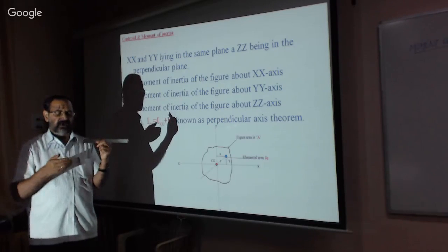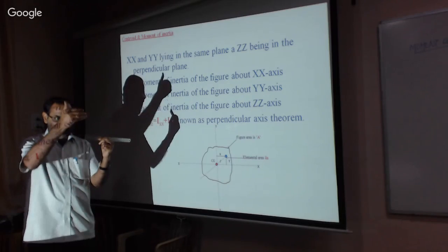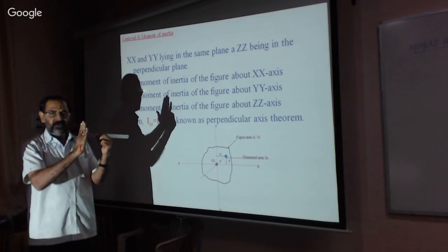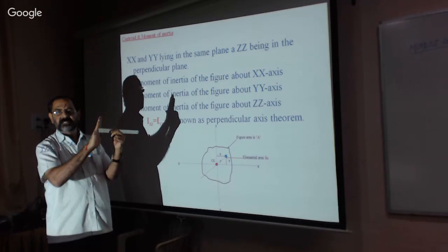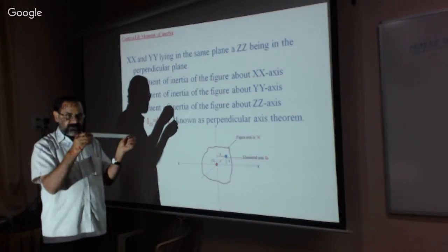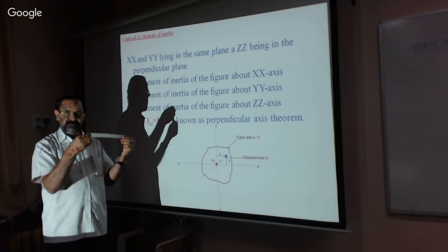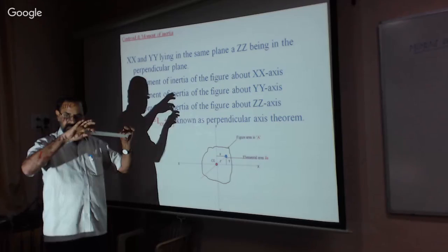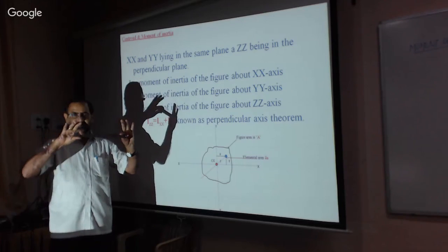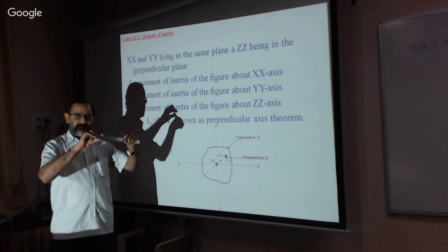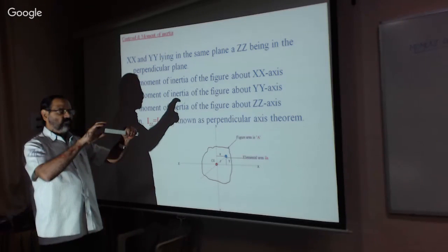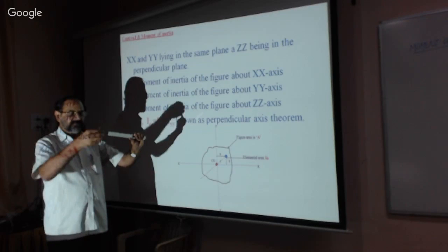Similarly, there is the y-axis. In this direction, the width is less. When you apply the force, it rotates in a shorter distance. That is why, if you apply the force in this direction, there is less resistance, and in the other direction it has more resistance. Along the x-axis it is more resistant and will not rotate. In the y direction, it will rotate.